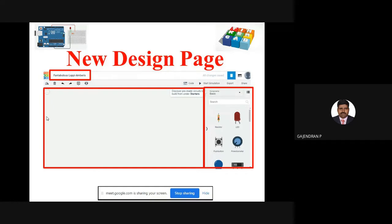Then we need to make the connections. And here we are not going to use only discrete components; we are going to use the microcontroller. Once you have made the hardware connection, obviously we need to write the code. So if you click this option, the code window will appear. There we can start typing the program. Once you type the program, if you click start simulation, the simulation will begin.